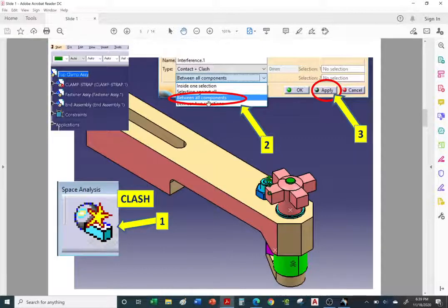And we can do, typically you want to do a clash analysis between all components. No matter which assembly or sub-assembly they're in, you want to check every component against each other. So we want to check that the knob doesn't clash with the washer, with the hook, with the strap, with the hex nut. So it'll check with every single component, and vice versa.